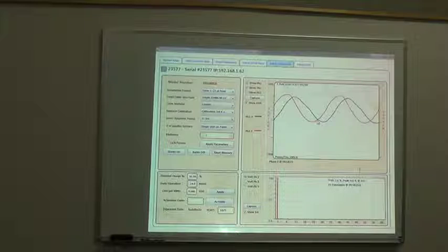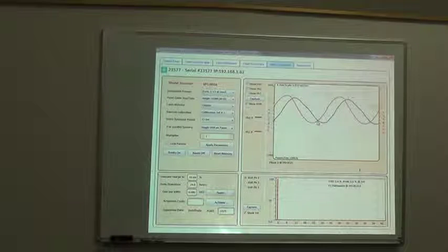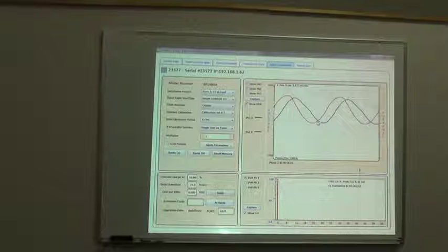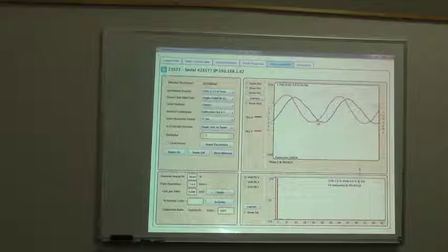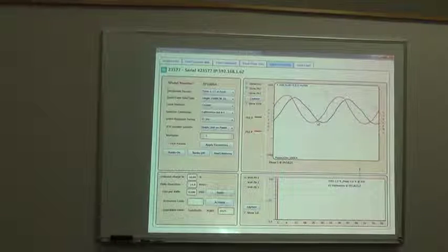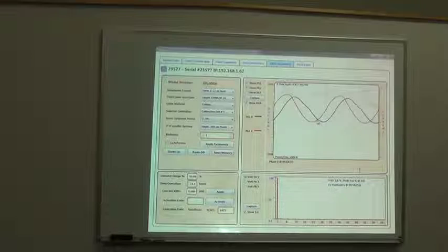We did that installation yesterday. It was a $16,000 bill per month, and we just calculated that it required one SP1000E, and the estimated saving was about $700 a month. About $350 comes from the fact that you have negative energy. The power factor is 80%, and the amp draw on that was about 100 amps. So the negative energy is substantial.